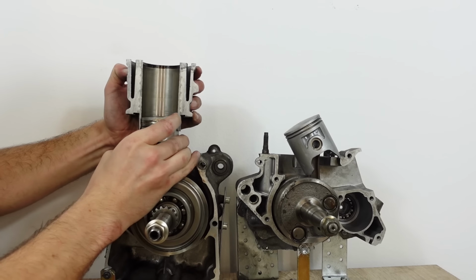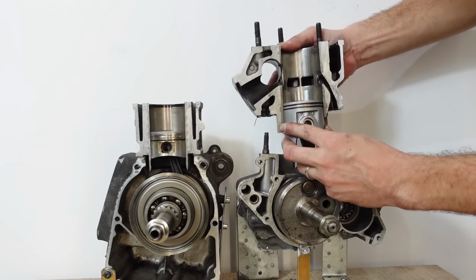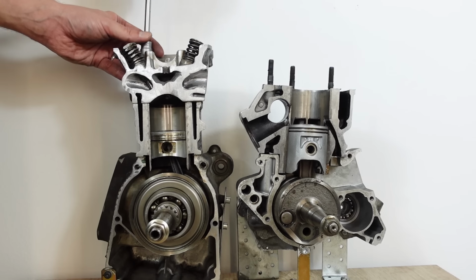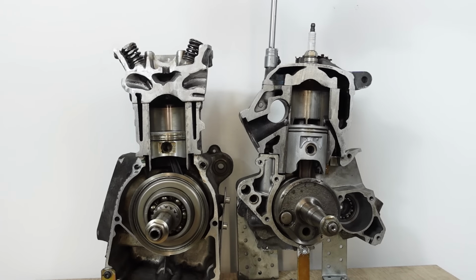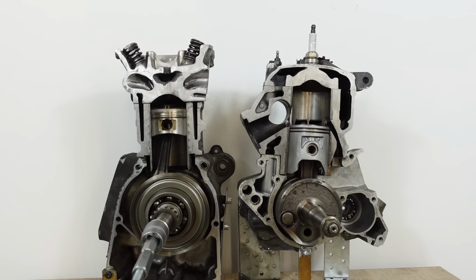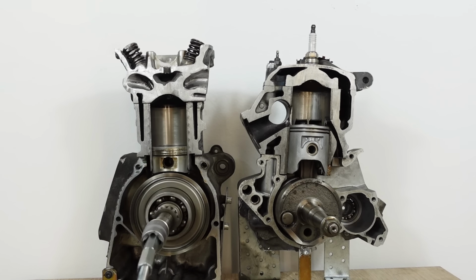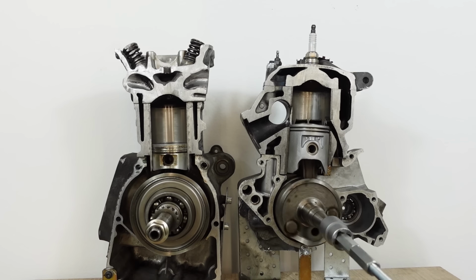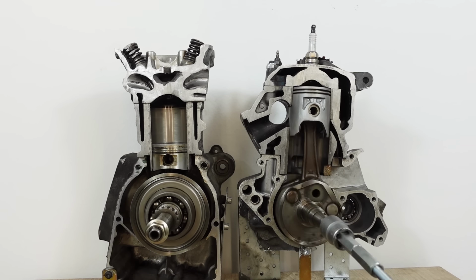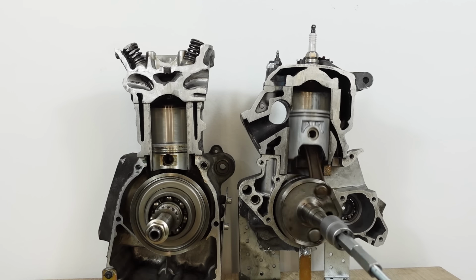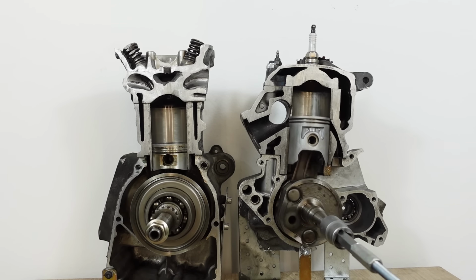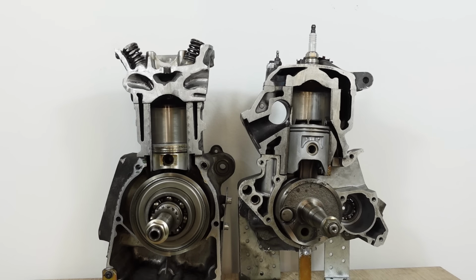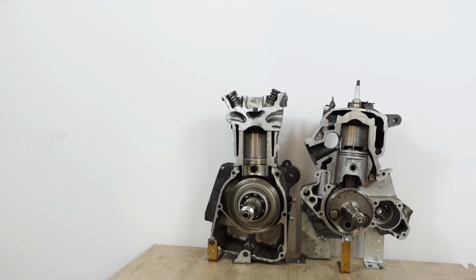They also both have a cylinder, and they both operate by converting the reciprocation of the piston into the rotation of the crankshaft, which then turns the gears of a transmission and ultimately the wheels of the vehicle. But beyond these core similarities, the 4-stroke and the 2-stroke start to fundamentally diverge, resulting in two very different approaches